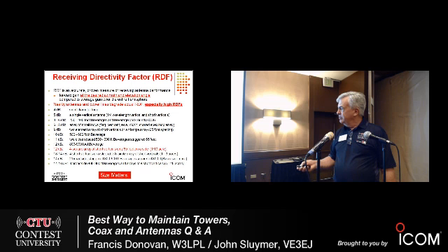And now we're getting into the high performance arrays. Either for a single direction, you can put up 4 short verticals if you just need to cover, like say Europe, for example. Or you could build a steerable array of 8 verticals. That takes about 1 to 3 acres to install.